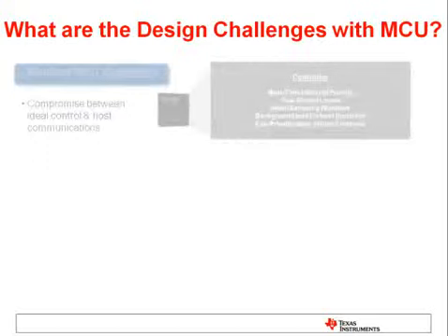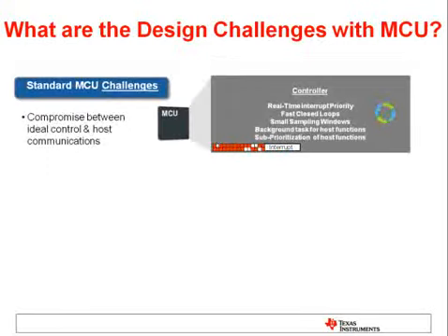In the past, there were two solutions to this problem. The first, in cost-sensitive applications, was to select one MCU that would perform both control and communications functions. From a hardware standpoint, it's a simple solution, but often requires a compromise on features and performance. In addition, software becomes more difficult as tasks and interrupts must be prioritized properly. While this solution is very appropriate for deeply embedded systems, it requires sacrifices by way of features, performance, and possibly a complex prioritization system for tasks.